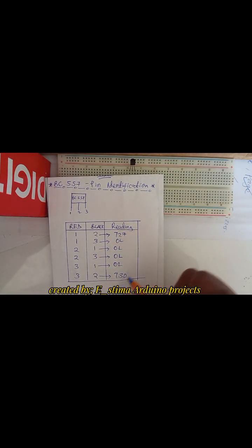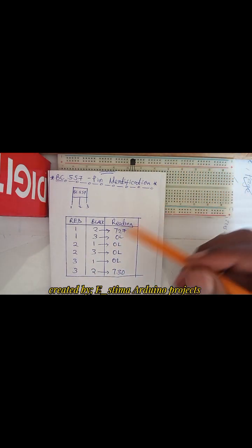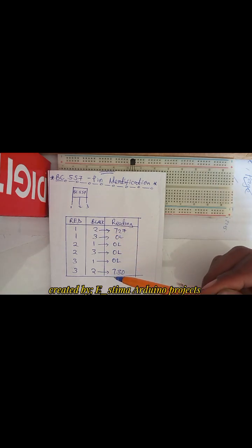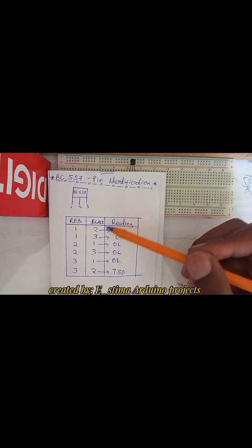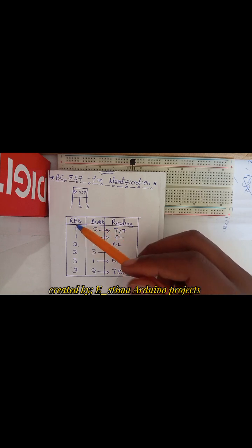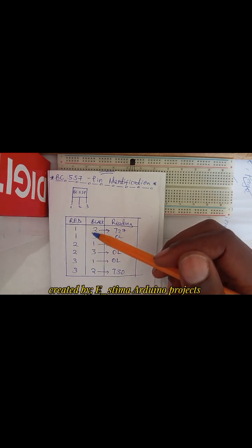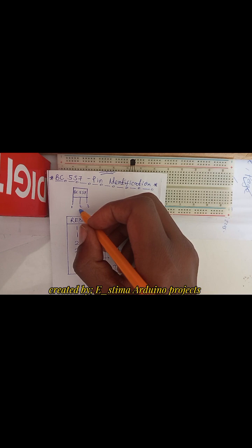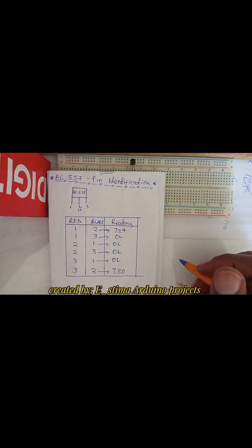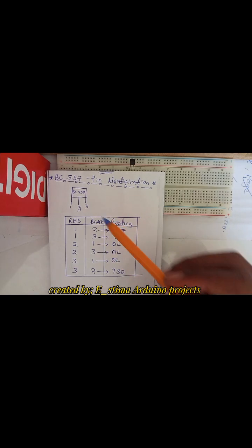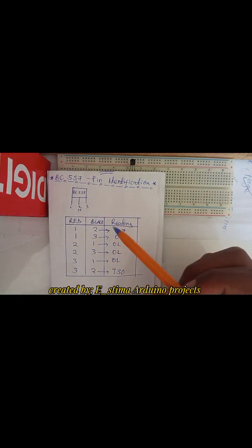From the readings we have obtained, we can conclude that it's only when black is on 2 that we have a reading. So 2 only gets a reading when either 1 or 3 are connected, and 2 is on black, which we said is our cathode. So we can say that 2 is an N-type material, because for the rest we are not getting current flowing through the diode between those two terminals.